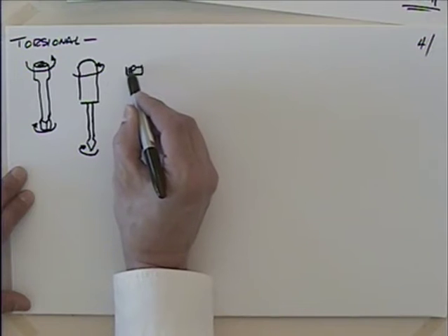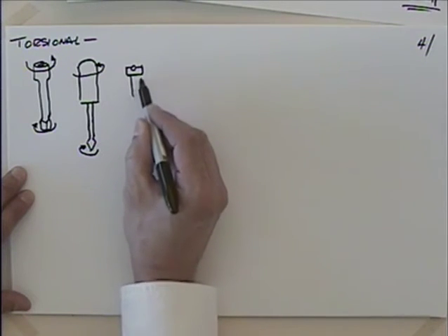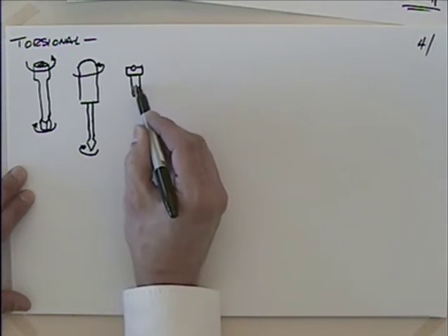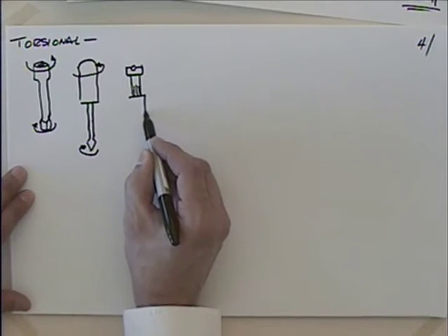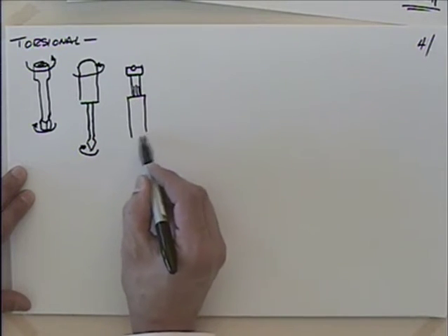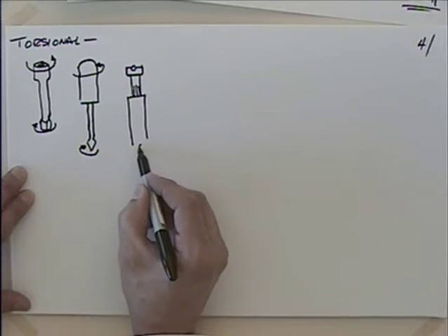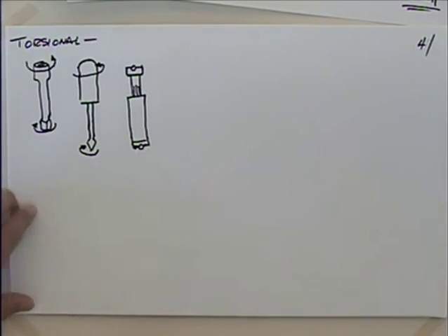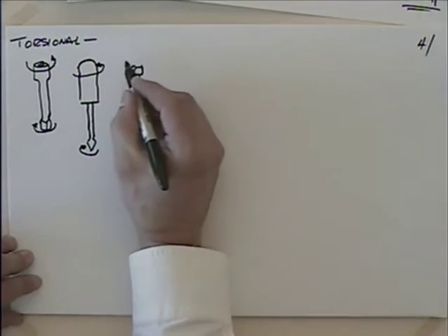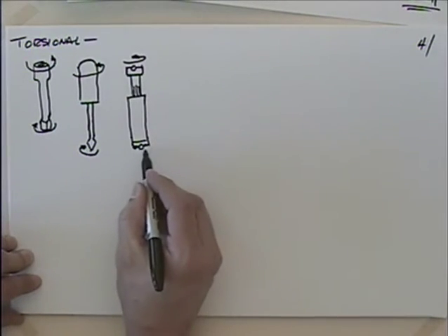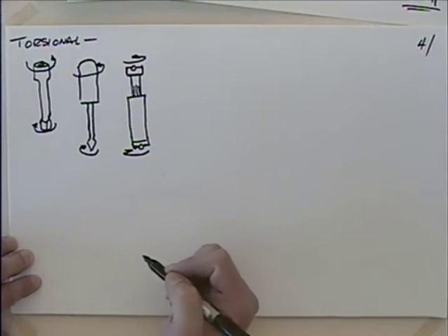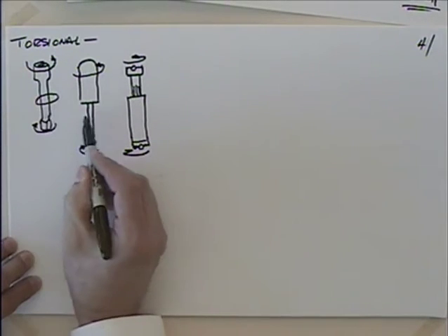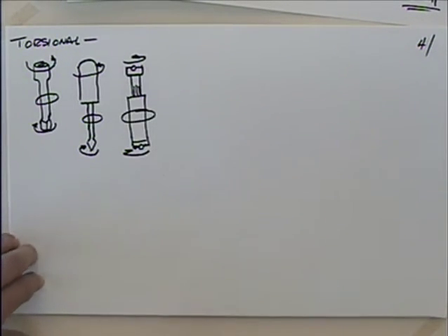There's the Hooke's joint or the universal joint, the cross. Maybe you have a spline section here, so it'll slide back and forth. And then you've got this going to a cross here. Okay. And if you're applying some torque here, and you have some resisting torque here, if you were to look here, or here, or here, you would have internal torsional loads, wouldn't you?